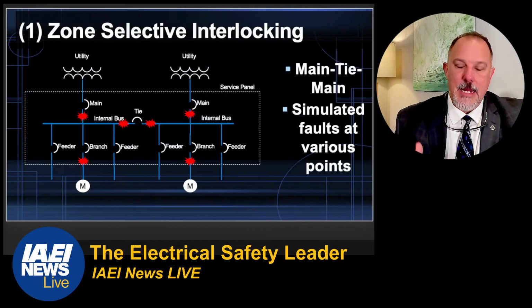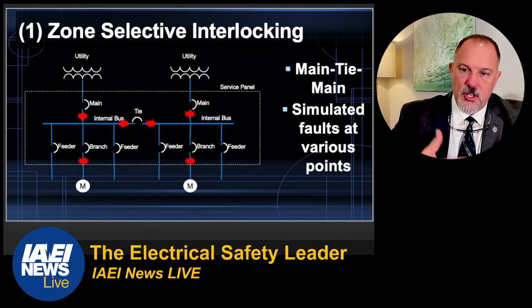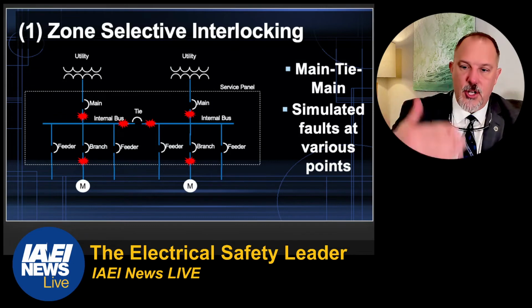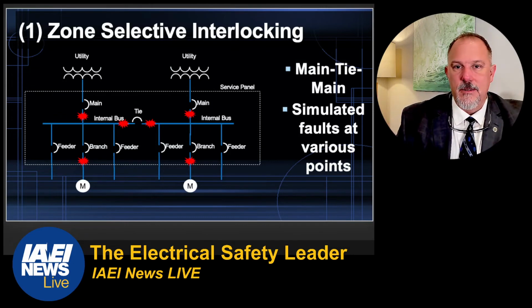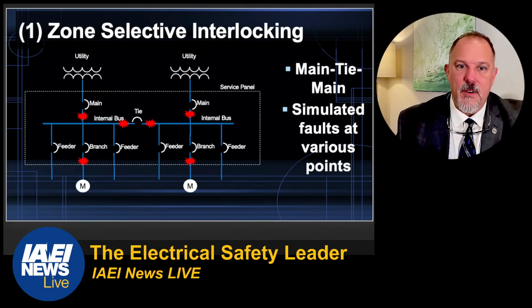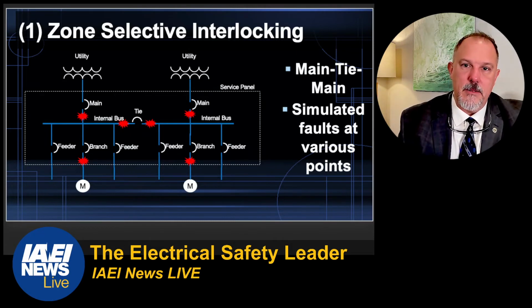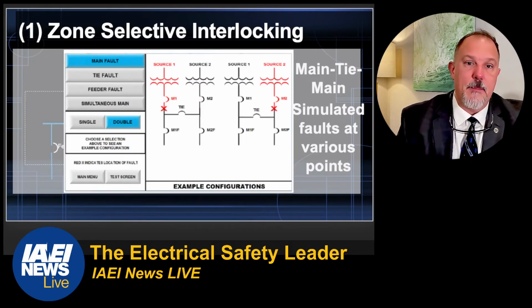Which, if you think about 70E, what does 70E tell us from a safe work practice? Is your first energization of this equipment a normal operation? Heck no. It's not a normal operation. You need to dress accordingly when you start to energize this equipment. Think about how complex it is. And yes, we do all of our tests. We want to make sure we've crossed our T's and dotted our I's, and make sure we didn't cross our I's and dot our T's before we energize this equipment. It's a very important, critical piece of that pie.